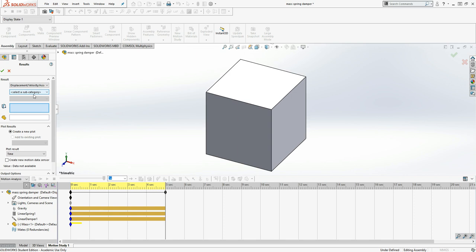First, all I want to see at the minute is that the displacement is realistic, that there are no errors, that it doesn't look quite poor, if you will, as far as an output. So then drop down again, and we have linear displacement, and we can choose magnitude, which is essentially everything taken into consideration, or we can choose just Y. Now, from what we've done in Simscape and Simulink and on a script, we were looking specifically at the Y component. So just for completion, I'll stay with the Y component.